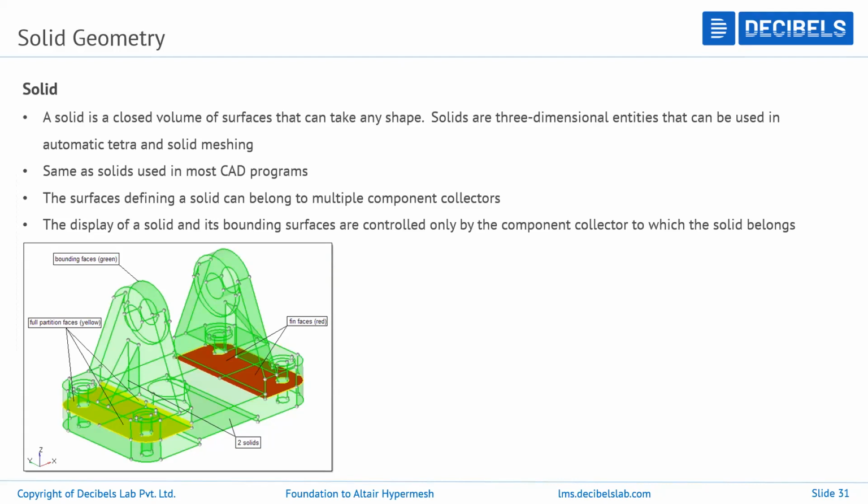since we have the option of extracting the mid surface. To extract the mid surface, the solid geometry is not required. But when it comes to creating 3D elements, we require a solid geometry. Why? Because there are two options available to create the 3D elements. We can generate them using the 2D elements, or we can generate using the solid geometry itself. On the top layer of the solid geometry, our elements will get created.